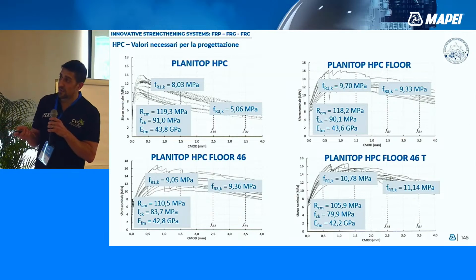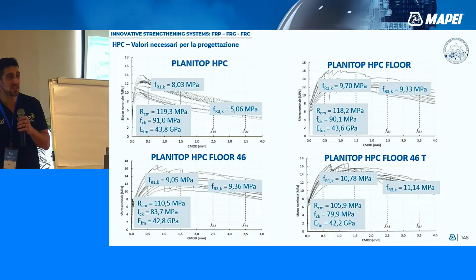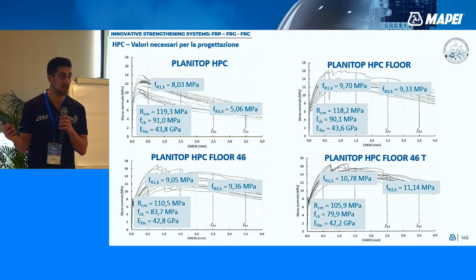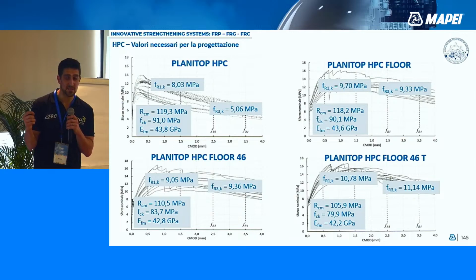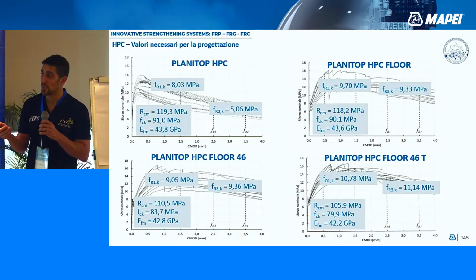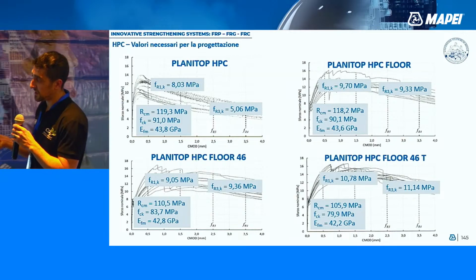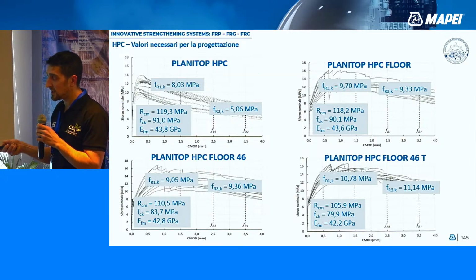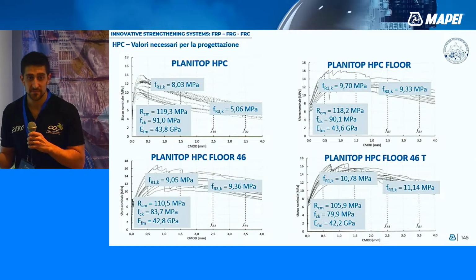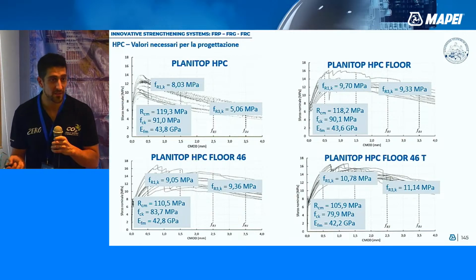And these numbers, FR1K, FR3K, are the characteristic values from which we can define the tensile capacity of the material. It is called the characteristic indirect tensile capacity. You can see that some products reach more or less 11 megapascal. For concrete, that is a huge value. Basically, for traditional concrete this value is 0.